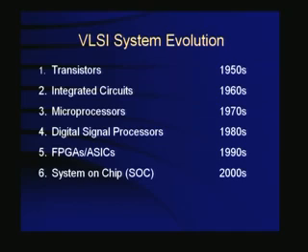Microprocessor is used more for data processing applications like databases, huge commercial type of computers. Whereas digital signal processor was used for signal processing, which is most important in say filters, FFT and things like that. So in that sense microprocessor and DSP have a commonality. Similarly, DSP, FPGA and ASICs have commonality in the sense they are functionally related, but DSP is programmable and can be used for different functions, whereas FPGAs and ASICs are meant for a specific function.